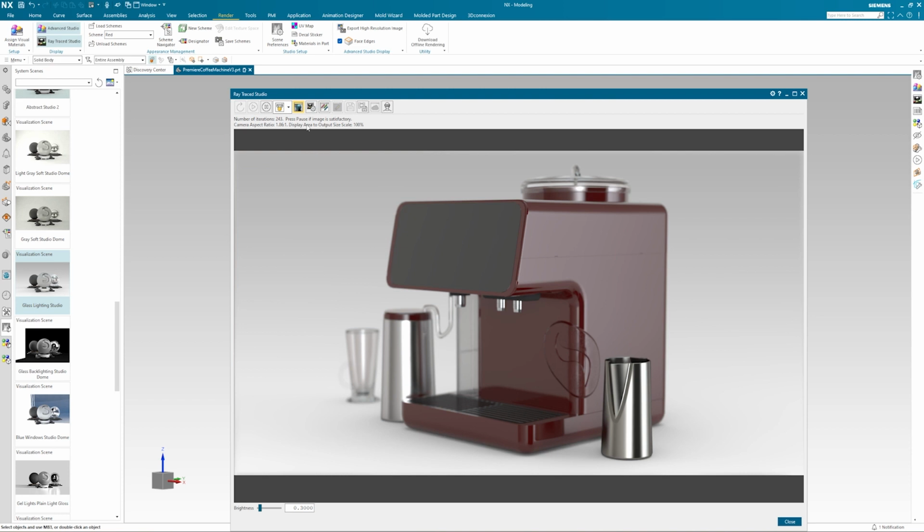If you're running NX on a lower powered machine, there's the option to switch to a lower fidelity render preset here to speed things up while you make any final tweaks. This will automatically reduce the amount of time NX spends on things like indirect lighting and global illumination.